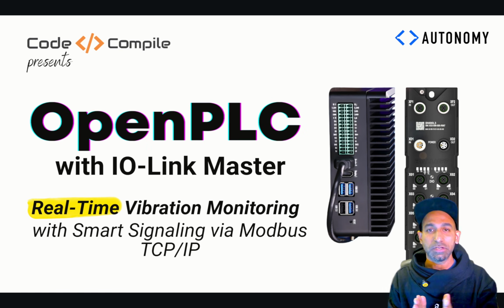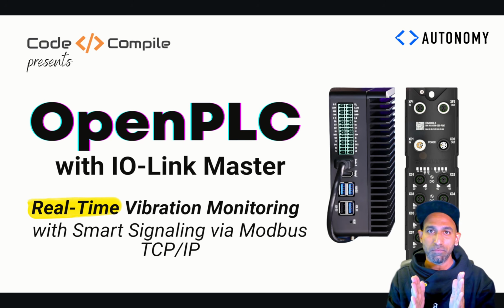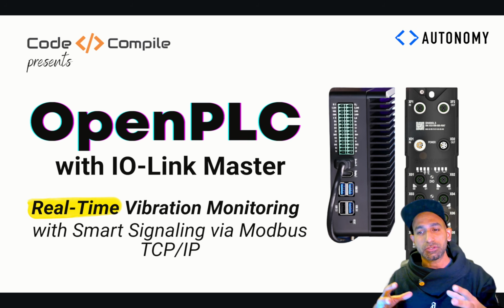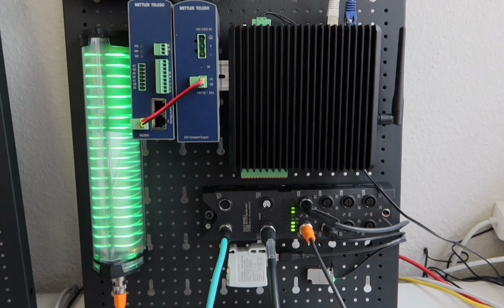So here's what we are doing today. We are going to read real-time vibration in virtual PLC via MODBUS TCP. We have our virtual PLC as OpenPLC runtime, which is running on my reComputer. It's the same device I was using in the last video. But now, instead of just doing the simulation or just running a dummy logic, I'm connecting that to real hardware. So I have a Balluff IO-Link master, which is connected to several sensors and an actuator I'm going to show you shortly. And I'm communicating my virtual PLC with this IO-Link master via MODBUS TCP to read the data.